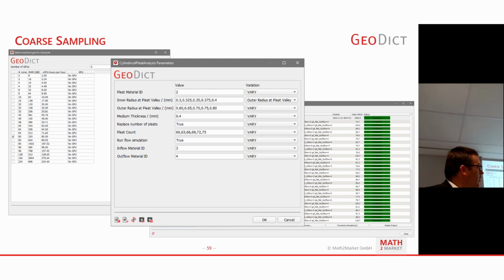But if I click run in the cloud, it opens up a window where I can specify the CPUs I want to use. Here in this case, I choose the 80-core machine. And after 1.5 hours, I get a completely green parameter window. Green means in this case it's successfully completed. There is also some other information. Of course, if the cloud machine is starting up, it's starting your simulation, it's running the simulation, it's finishing the simulation, and this will also be highlighted in yellow.